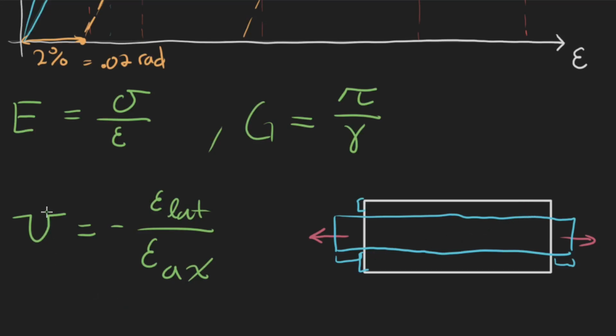In some cases, you can get stuff like negative Poisson's ratio because of weird materials that we've made, like foams that expand when you pull on them. But for the most part, Poisson's ratio is going to be between like 0 and 0.5. It would be 0 for something like cork, where you can basically just compress it and it won't get bigger or wider or like thinner.